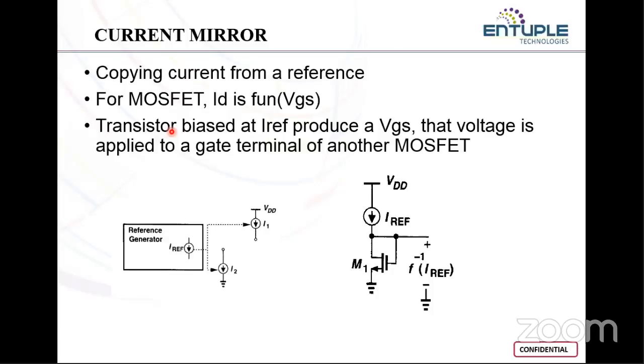Instead it takes care of the currents and voltages that are required for each and every block or each and every device to turn on or turn off at a particular point of time. That is the purpose of bias voltage, right? So how to generate those things using a circuitry? The current mirror does that part in a more efficient manner.